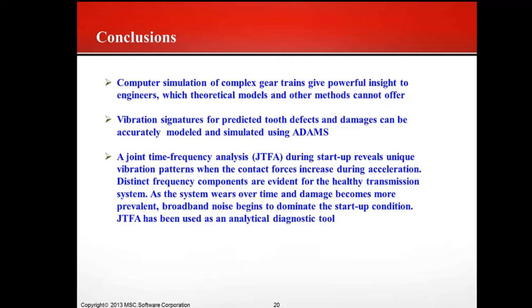They apply the health monitoring system in the wind turbine gearbox. They actually observe a lot of sidebands due to the crack, but they desperately need the modeling to explain what causes that. They have certain experimental results, but some of the engineers told us they only do that from field measurement, and they don't have the simulation because FEA takes a while for them to finish. They couldn't get the results.